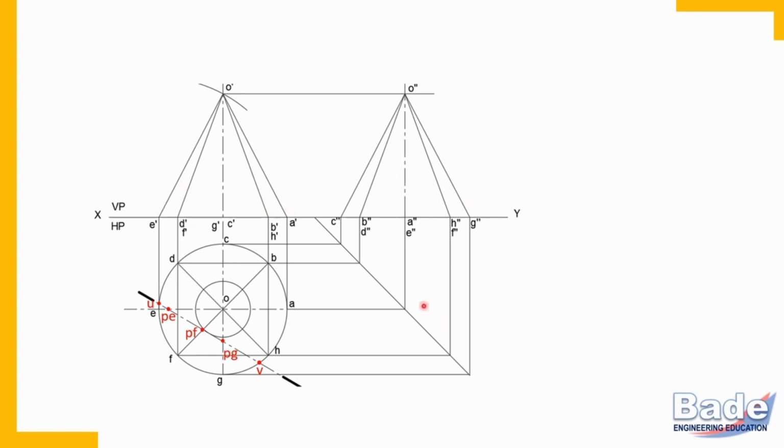But now a very important thing here: the cutting plane line is in the top view. The height of the object doesn't appear in the top view. We always get height in the front view. But in the case of a hyperbola, it's very important to get the highest point, and that is nothing but the vertex of the hyperbola. So which point is the highest point? Height doesn't appear in the top view, then how to locate that highest point? Try to understand, this is really something new here. What logic are we going to use to locate the highest point?